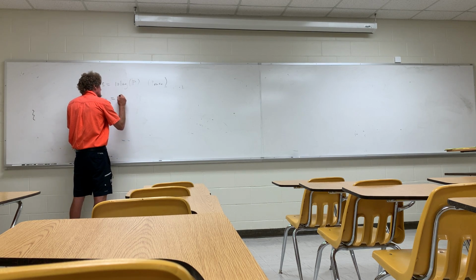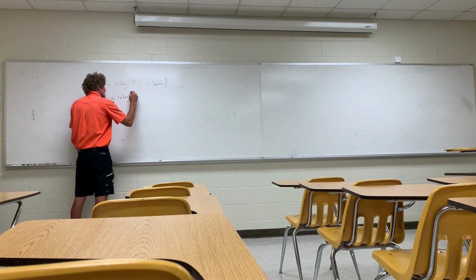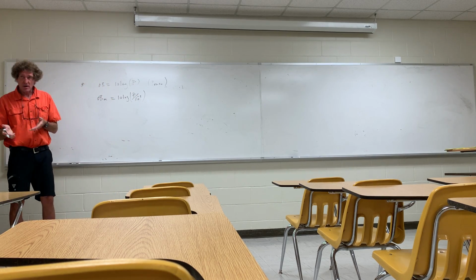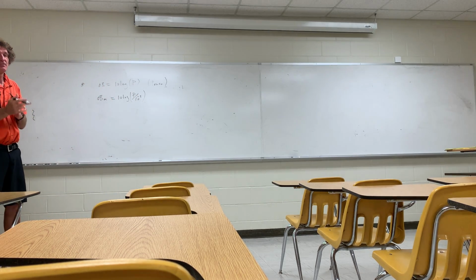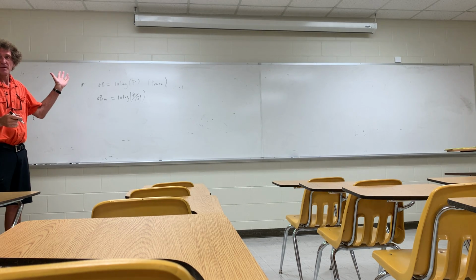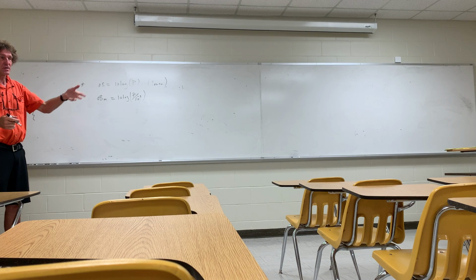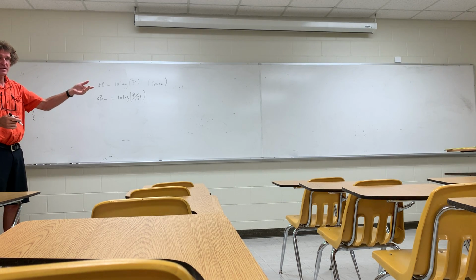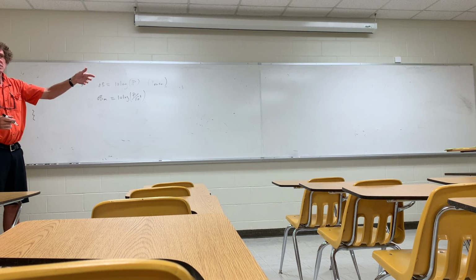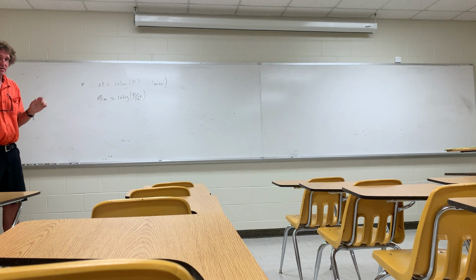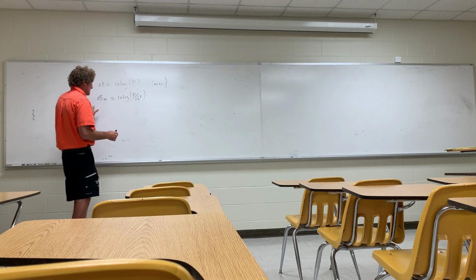And that's 10 times the log of the power term divided by 10 to the minus third. Because 1 milliwatt is 10 to the minus third. Now, dBm is a very common unit. How many have heard of this? Most of the time, when you see power measurements done related to like cellular activity and stuff like this, the expression will be given, or the quantity will be in dBm. That's almost guaranteed. And this is power.